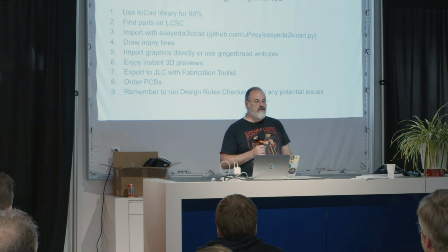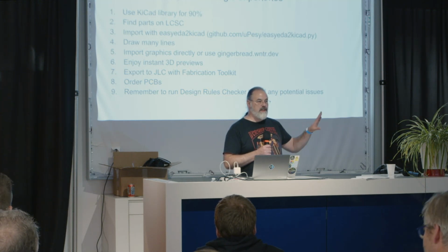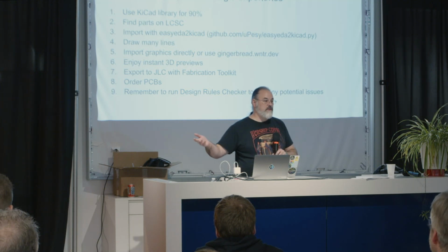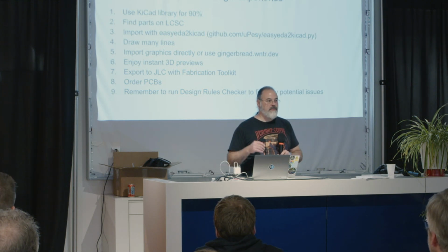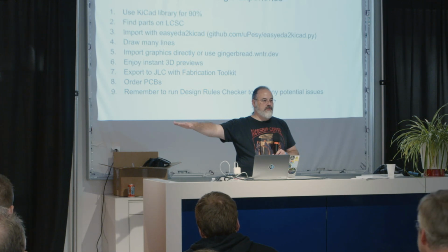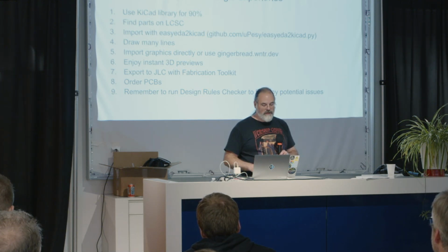And this is the one that you want. So this one is updated and goes to LCSC, EDA. They have their own online cloud thing or whatever, and it pulls down footprints and symbols and 3D models for the kinds of parts where you need some random switch or random battery holder or something like that. You can go in there and find that stuff. It's really helpful if you are then going to use JLCPCB or something like that to get your boards made, or do PCBA through them as well.